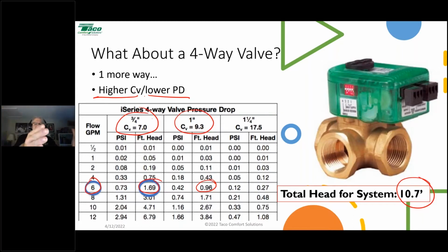Now I go down to 95. Whoa, got to start opening up again. And you're going to be bopping back and forth. You'll eventually get to the water temperature you want. With a smaller valve, that hunt is narrowed considerably.